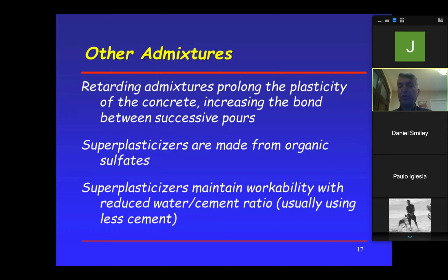Of course, when we do that, we call that a construction joint. They put a form at the joint, and then they come back in the morning, remove that form, spray it with water again, and then pour against that. Now, if the concrete still has a nice plasticity, when the new concrete bonds to the old concrete, it's going to bond well. If the old concrete is already dry and the new concrete is wet, it's not going to bond well. All right, that's what it means here. Again, the mix designer is going to do all that.